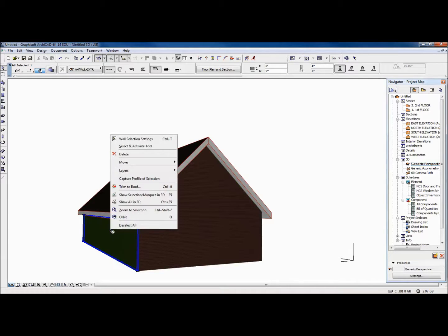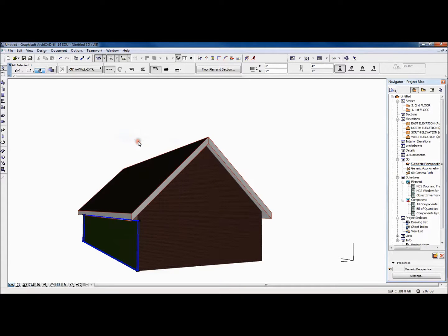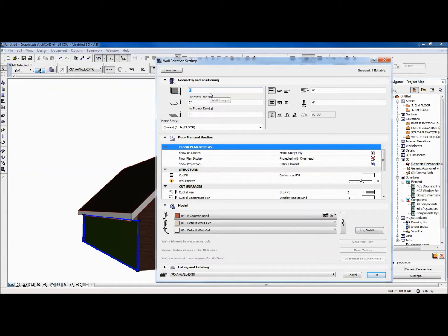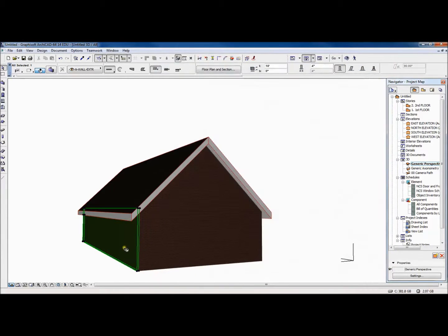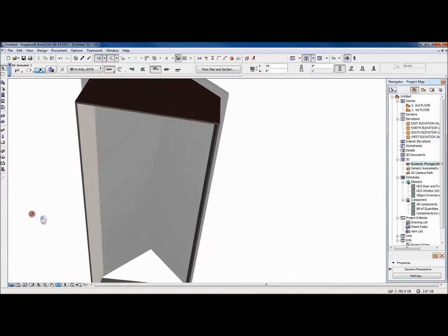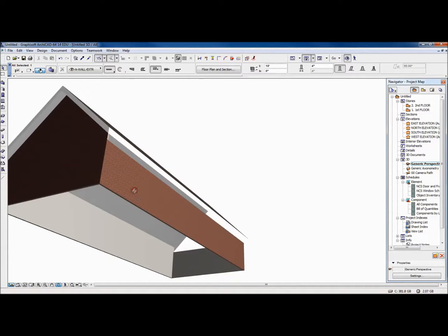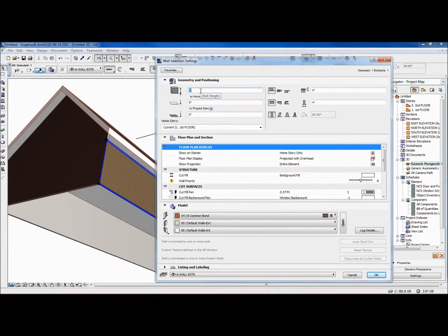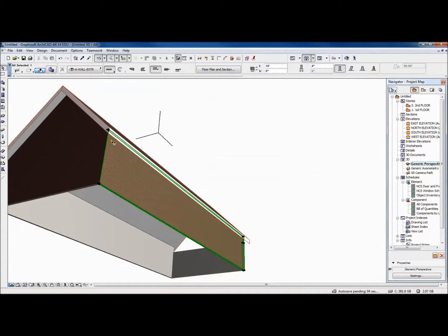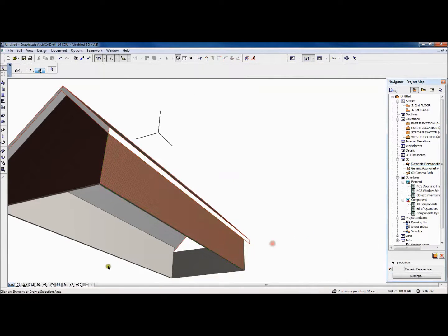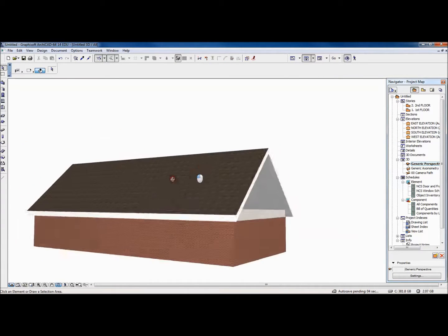And so now we can do exactly the same thing again. We can set this up to maybe 10 feet here, and it will shoot through the roof section, and then we can trim to roof and trim. And so now when we look at it, we can see that there are no holes in it. Over here we still have a gap right in this section, so we can increase the roof elevation, say to 10 feet. Okay, it puts it up in the roof. Then we'll trim to roof and trim, and one more wall, and we should have this.